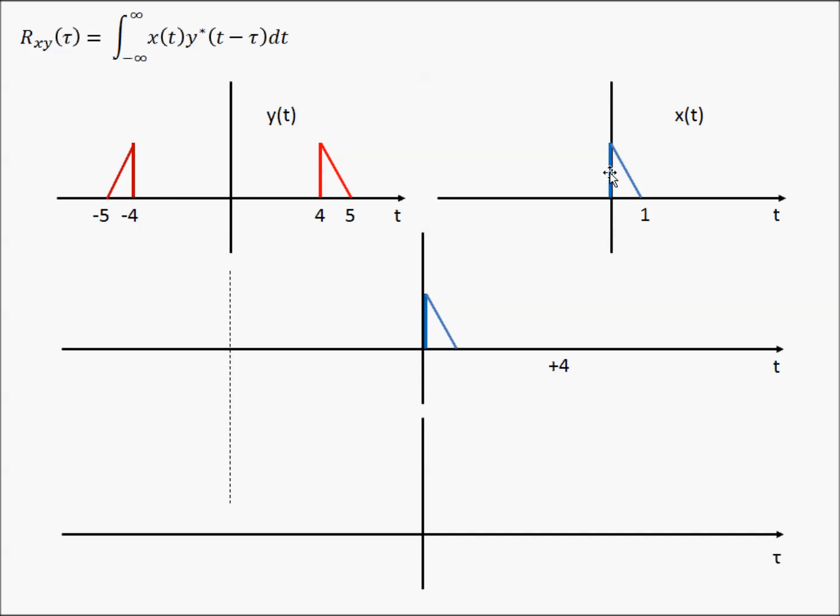We're going to do the cross-correlation with signal x(t), which is identical to the triangle on the right. So again, we should know that we have non-zero values for the cross-correlation up until the signals overlap. So where this first triangle starts to shift across, we'll start to get non-zero values. And I'm not going to work out the values exactly, the equation of the curve, as I did in the last example, but you could do it very easily by using the definition of the integral.